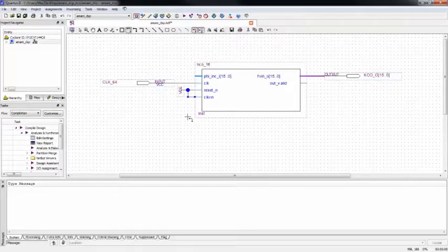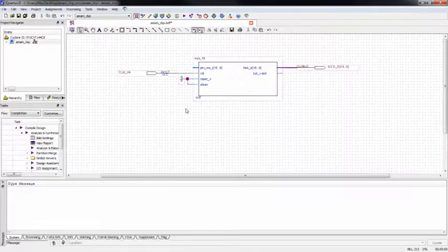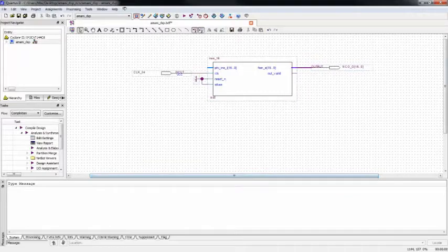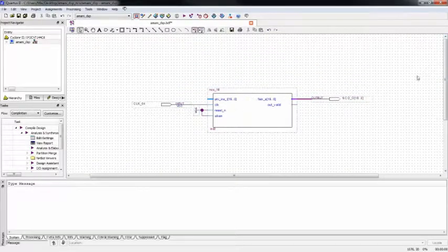So typically in industry, you're not going to use the block symbol and schematic capture method to do FPGA development. You're typically not even going to open the Quartus II tool itself. You're going to use some sort of Perl script and run the synthesis tool externally via scripts. But for the beginner and for hobbyists, this is a pretty straightforward way of designing a system on the F2.